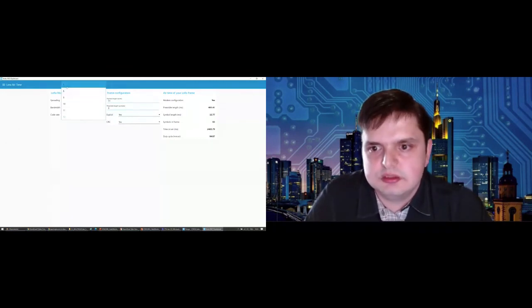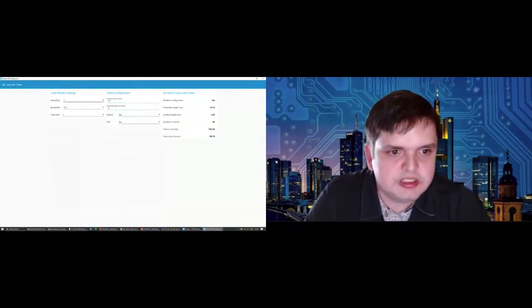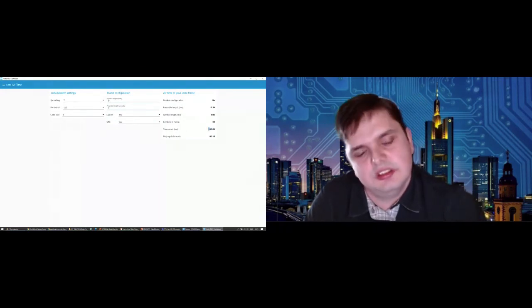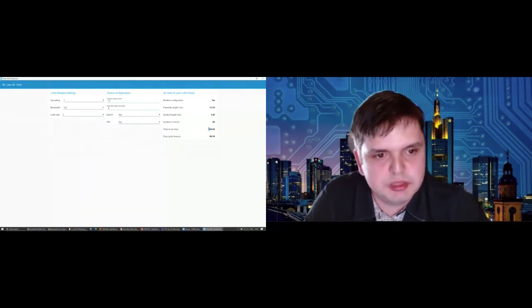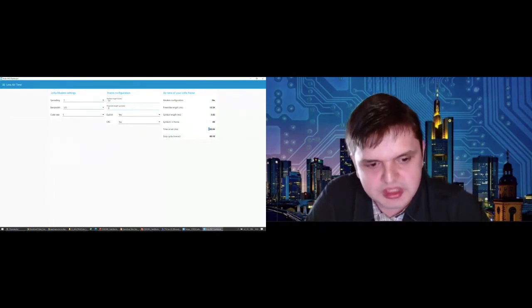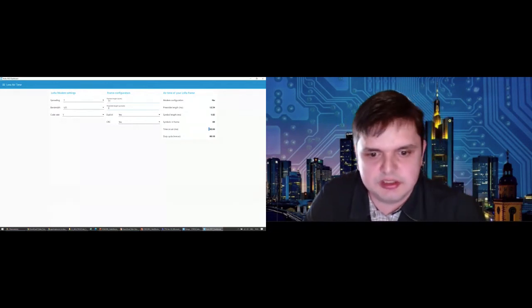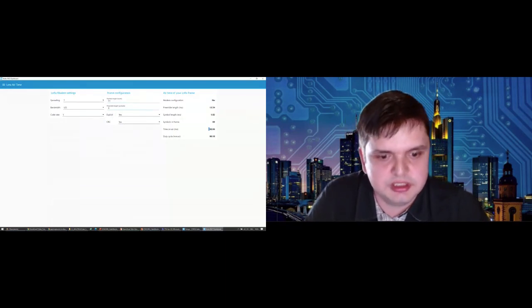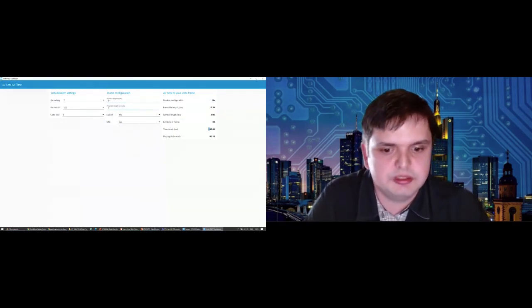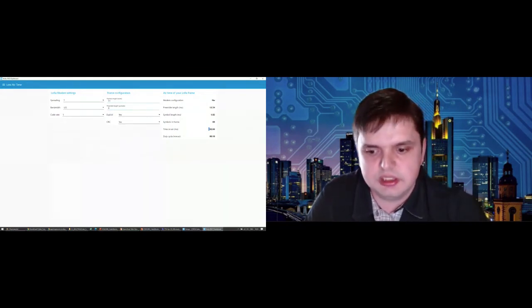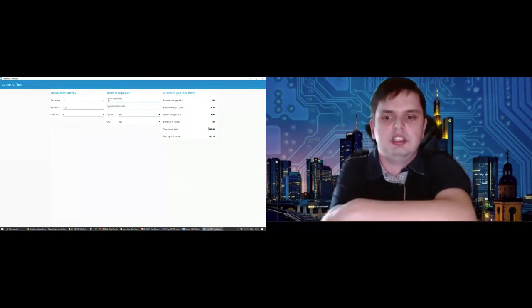So if we change, as before, the spreading factor to 7, instead of 2.5 seconds, we now have 102 milliseconds. So it's more beneficial to transmit with a lower spreading factor, but at the same time, it will rapidly decrease the range. So you need to find the threshold suitable for your design. Usually in LoRaWAN, we have the adaptive data rate, so it is changing based on the RSSI.